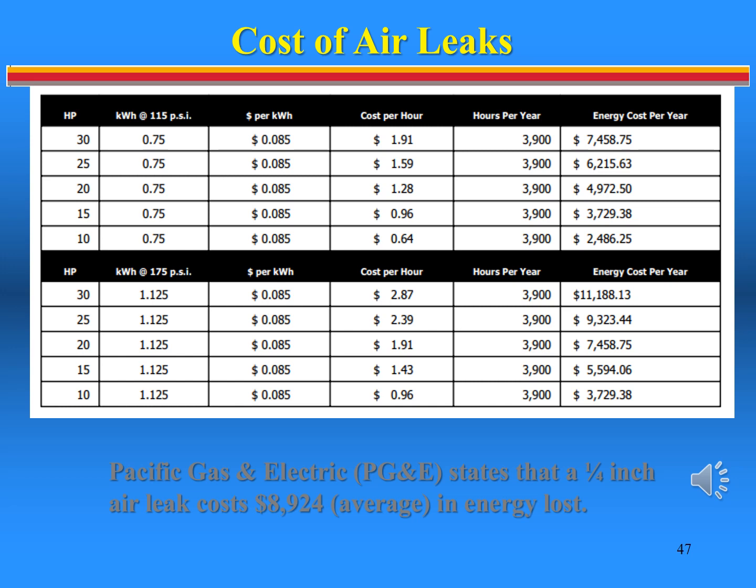A typical plant that has not been well maintained will have a leak rate equal to between 10 and 30% of the total compressed air production capacity. The easiest way to identify leaks in a compressed air system is to walk the plant and listen for them, especially during non-production times. To estimate a plant's leak load, operate the air compressor in a load, no load, or start-stop mode during a non-production time. Record the loaded versus unloaded times and compare these to the compressor's capacity.